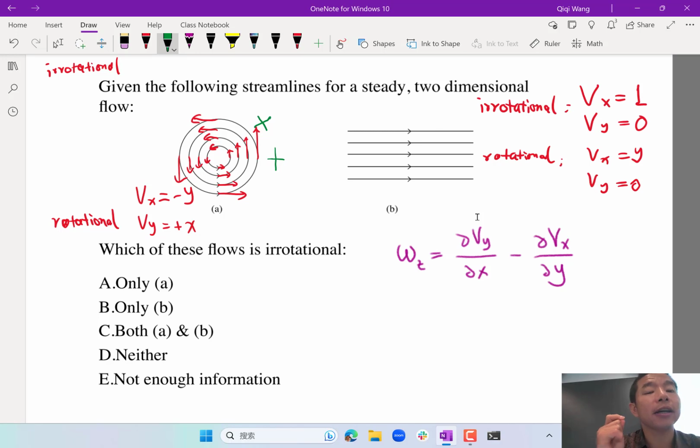So if you want to construct an irrotational flow, the vertical line has no choice because I have already defined the streamline. If you have a vertical line that is already following the streamline, no matter what you do, it is going to keep following the streamline. So the vertical line is still going to be like that. But in order for the flow to be irrotational, you want the horizontal line to rotate in the opposite direction. You want it to tilt the other way, which means the inside has to be faster than the outside.